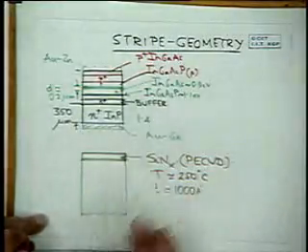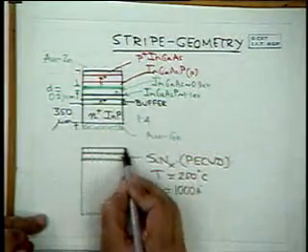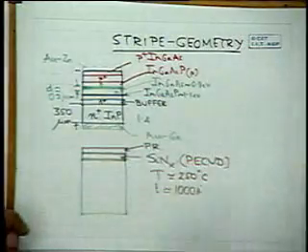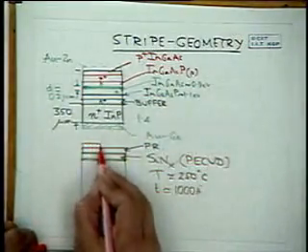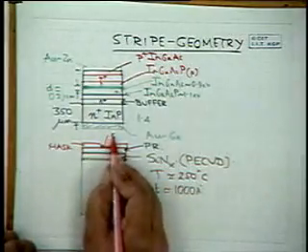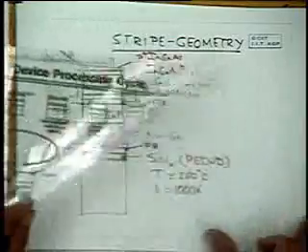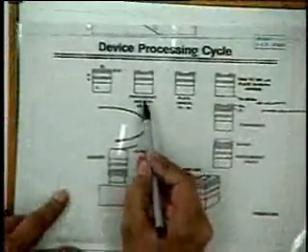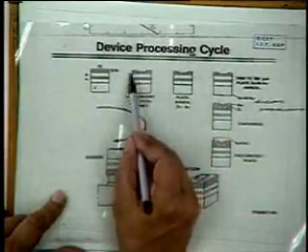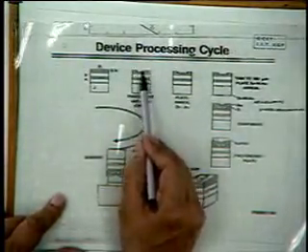Then, with appropriate masks, you deposit a photoresist. Then you have the mask coming on top, with the defining geometry. This is the stripe width S, which is of the order of, say, 5 to 30 microns. So that is this step. On silicon nitride photoresist, you expose the photoresist and etch the stripe, and as a result you will get silicon nitride remaining in this portion, and no silicon nitride below this.